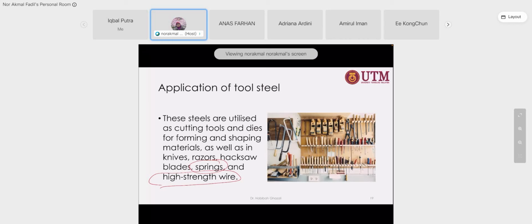Let's take a look at the application of the wire. For example, bridge suspension and cable cars carry heavy loads and form a load bearing structure, as well as experiencing static plus dynamic plus accidental loads. So high carbon steel can serve for that kind of application.